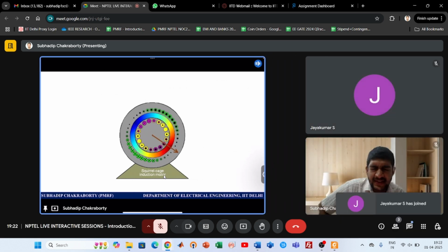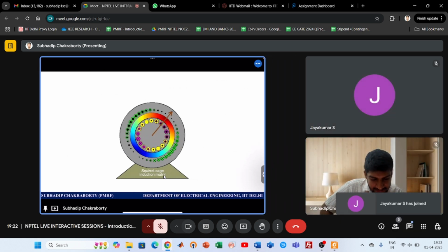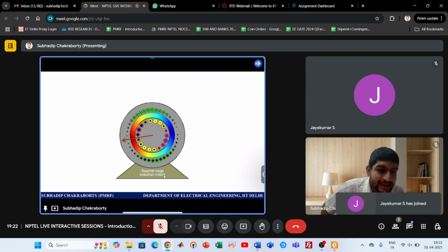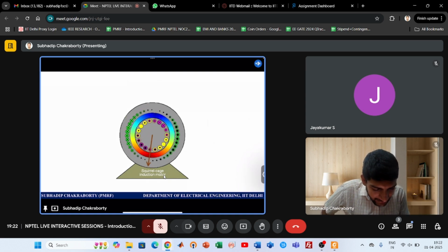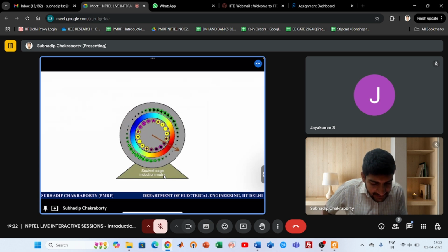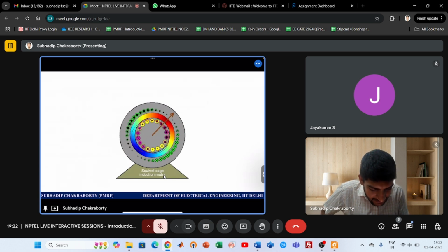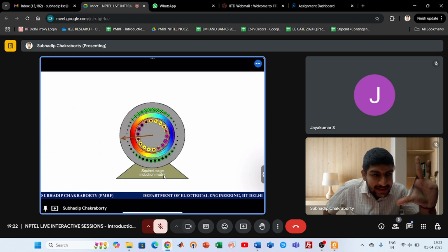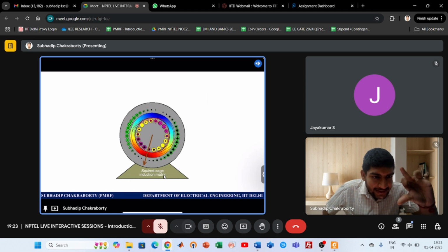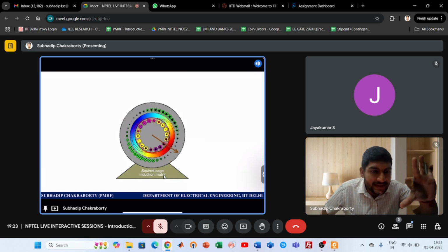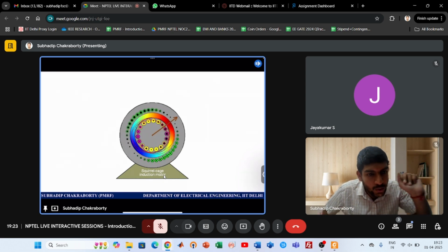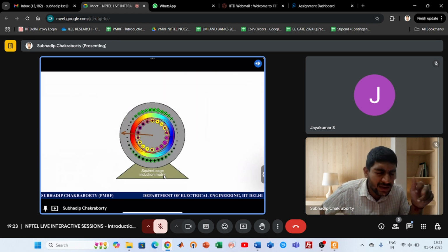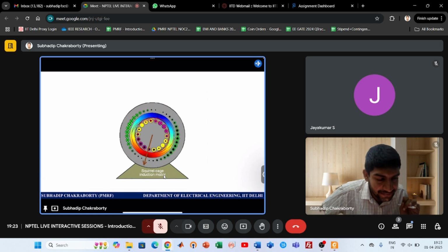So you can also see this animation where we have just created the polarity. What is the polarity and how do the coils behave, because the polarity is changing, right? You can see the polarity is getting changed. Look at these coils. They are continuously increasing and then decreasing. That is how a sinusoid behaves. A phase voltage is increasing and decreasing in the A phase coil. B phase voltage is increasing and decreasing because it is a sinusoidal voltage, but not in phase with A.